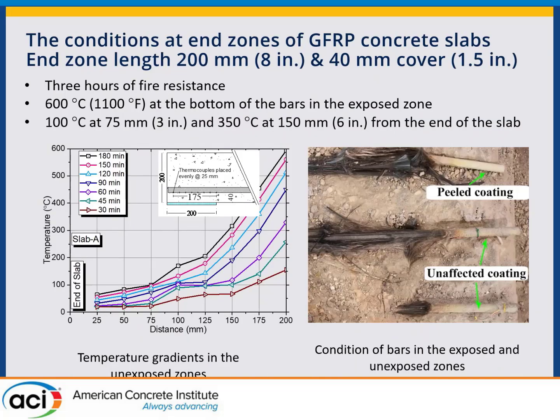we're still retaining. So in these tests, what we had was end anchorages at each end of about 8 inches, 200 millimeters, that were protected from the fire. And we tried to reduce that as much as possible, but this is basically as short as we could get them in the test, because we knew we wanted to focus and see what happened more on the bond performance.